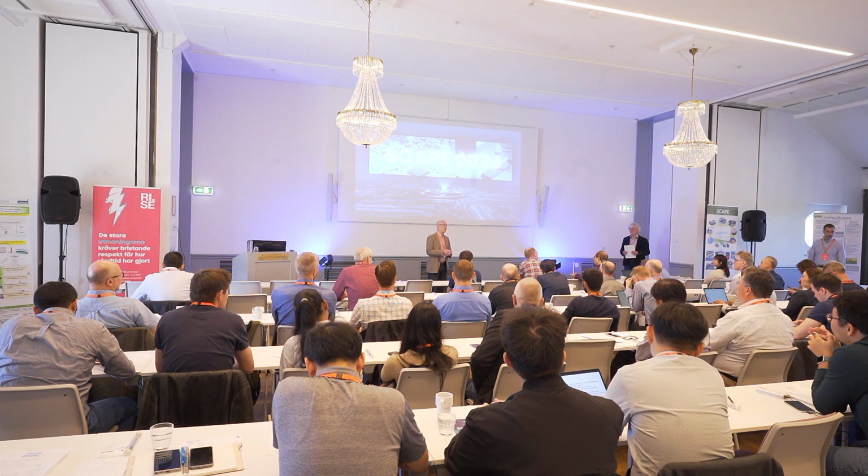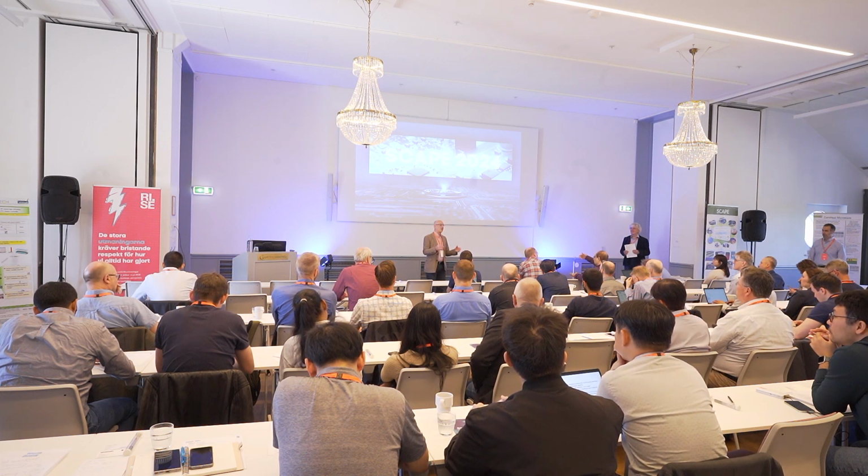Which way? Two engines, one on each side, and if one of the phases fails, it still works. You mean that... Yes, we have two electric motors, but even one failing is very severe. That is like once in 100 million flight hours. So in principle it should never happen that one motor fails, but a part of one motor might. That's my message here: we will design motors differently than what you're used to, which also has an impact on the inverter design, because the inverter design will be more standard.